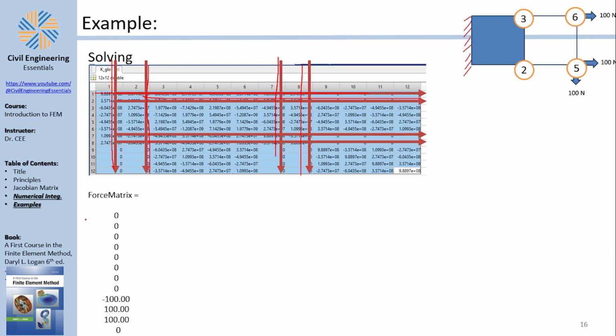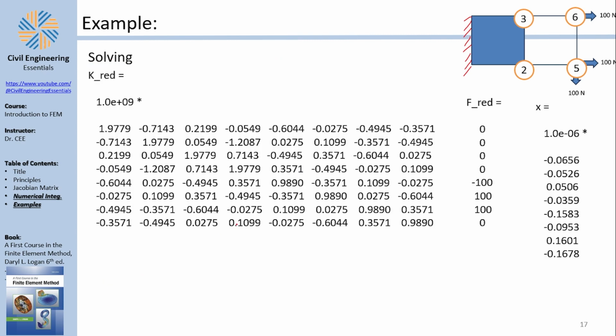Of course, you have the force matrix, you would have to slash and dash those two things for U1, V1, and U4, V4. The resulting system is something you can solve. You have the simplified condensed K matrix and the condensed force matrix, which means you get a displacement. Of course, the displacement is ridiculously small. The reason is that I have a steel plate with a 100 Newton force. This is nothing in comparison, but yeah, it is what it is.